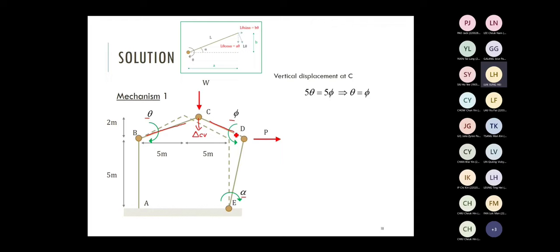Now we are considering inclined member. For inclined member, how to find out downward displacement? The top picture shows you the tips. Actually, I extracted it from the lecture notes. If you consider inclined member with inclination angle alpha, this hinge is under rotation theta. If you want to find out the downward displacement, the calculation is simply equal to the horizontal distance A times the plastic rotation beta.